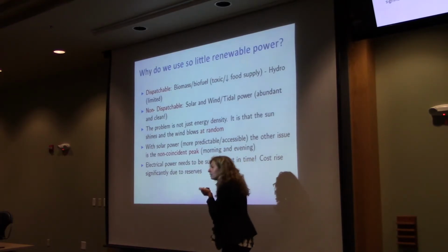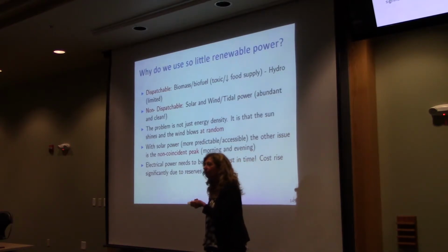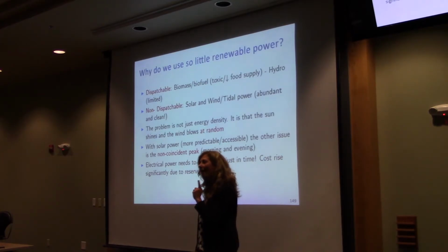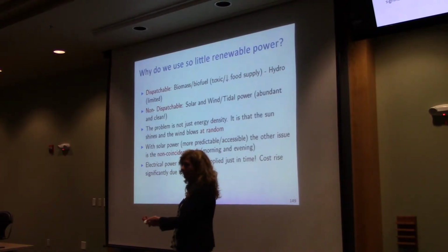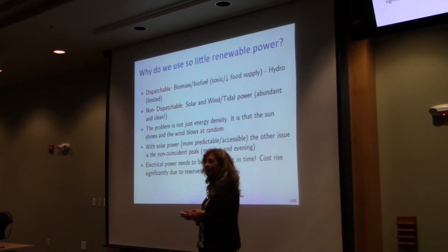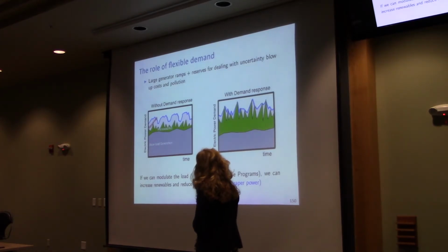So if anybody tells you, oh, I have a net zero building, net zero energy building, you have to ask them, but is it net zero power or is it net zero energy? Because it's a very different thing. Because if you are absorbing power from the grid at moments of congestion and emitting power when nobody wants it, in excess, then you really are not helping so much the equation, okay? Okay, so that's why we want a responsive demand.